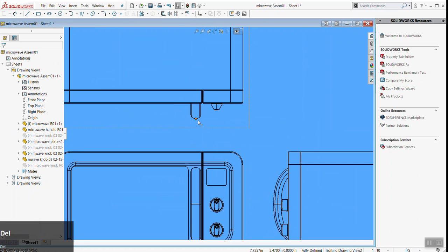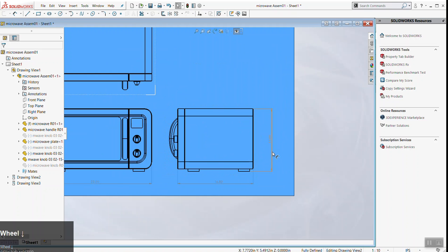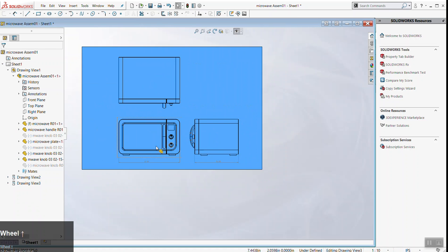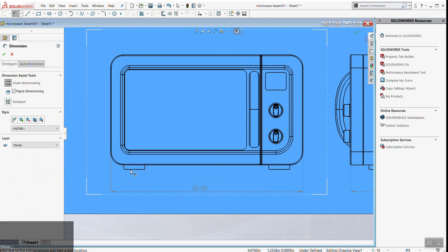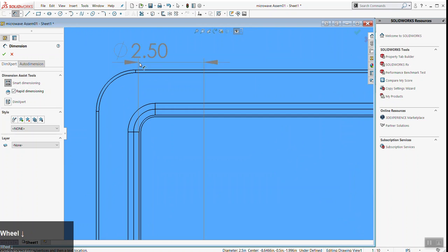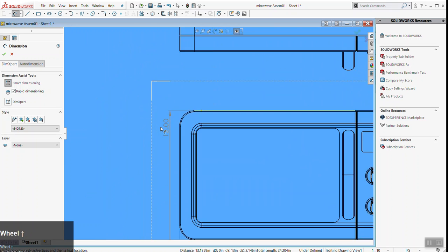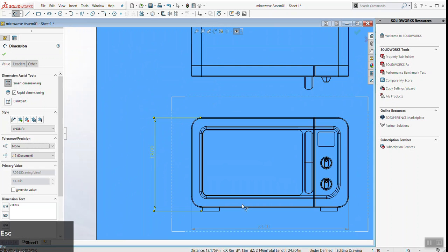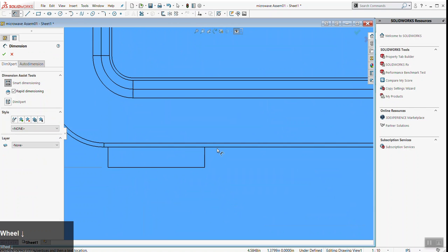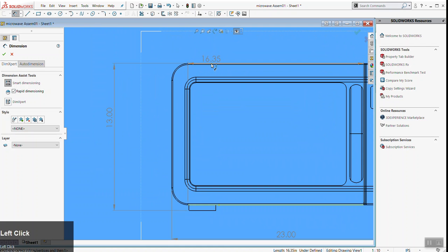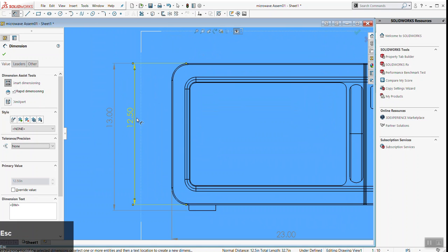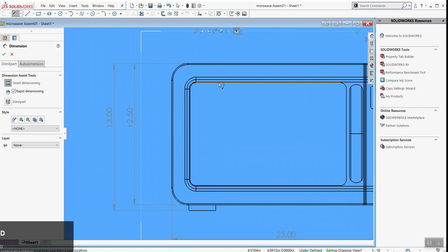So, for example, this being the main view, the front view here, I think it would be more typical to put both the width and the height on the front view, because this drawing has the most information. So I'd go to the bottom of the feet here, and I would also probably give, for my client, this dimension here. Maybe they want to know how big the window is. So here's an instance where it's impossible for me to avoid crossing the object. I have to give them that window.